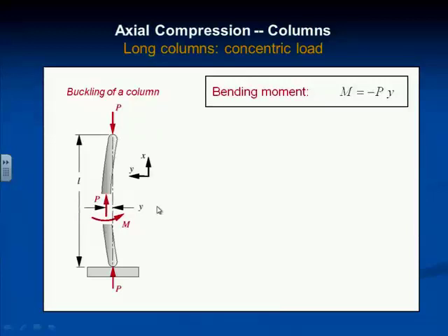Increases. More moment means what? More deflection, which means more moment, which means more deflection, which means more moment, which is why it goes suddenly to failure. It's a positive feedback situation. So once you start it, there's no stopping it.